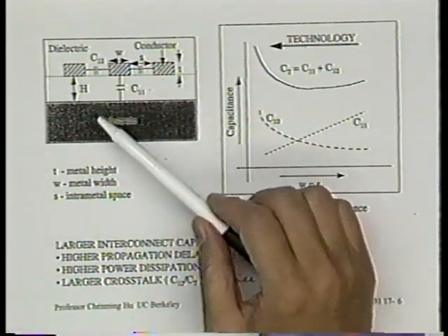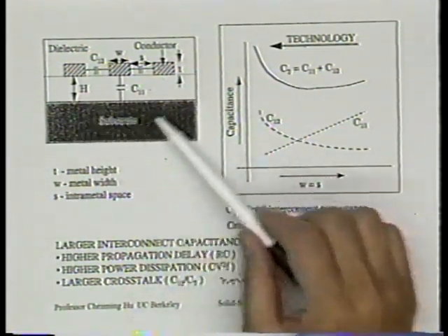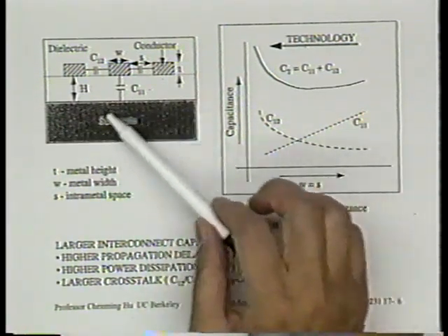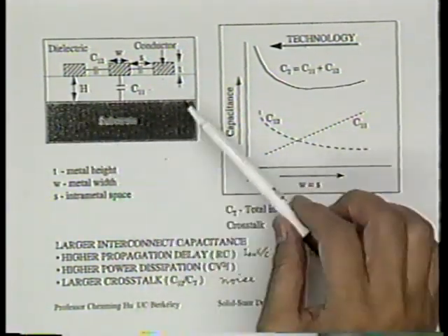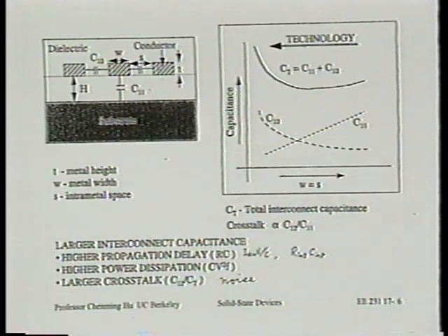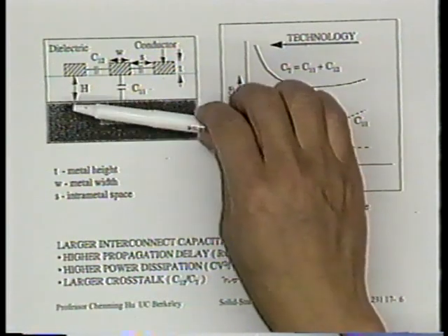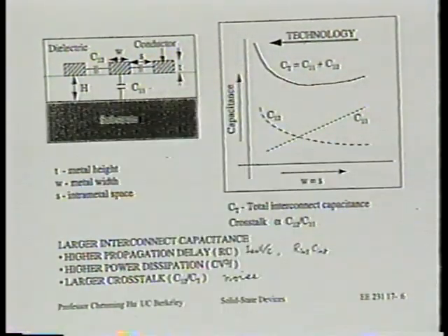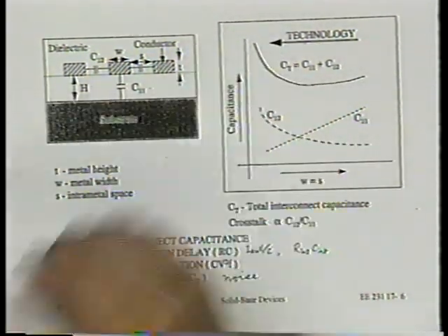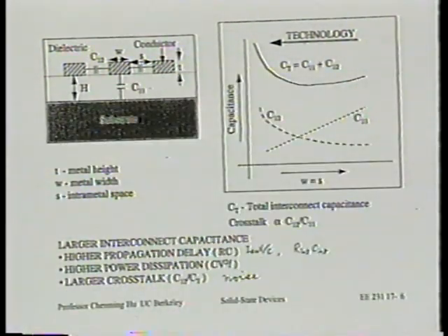By the way, if there are several lines in the bottom layer, that bottom layer can be considered just as a continuous metal line as far as capacitance is concerned. This has been verified by solving the Poisson or the Laplace equation. All right. So we often model this capacitance as if the bottom layer is just a complete conductor rather than lines of conductor, all right?